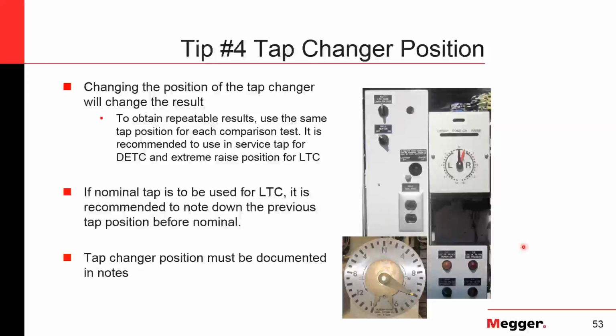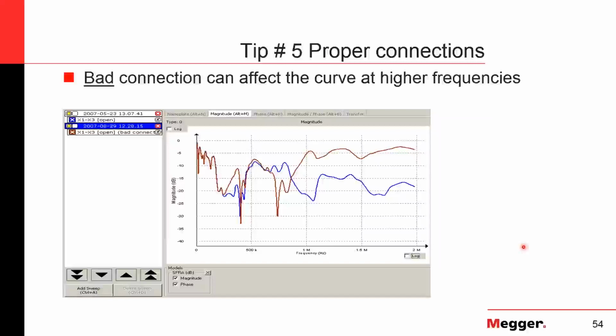Well, what it was is this was a bad connection, and this was taken at first with a typical alligator clip, like jumper cable type clamp. If they actually went back and cleaned the connection, made sure it was a good connection, now you can see once again these pretty much overlay each other. And this is why you want a nice good connection, use like a C clamp that you know when you go down, it's connected, you're solid there.